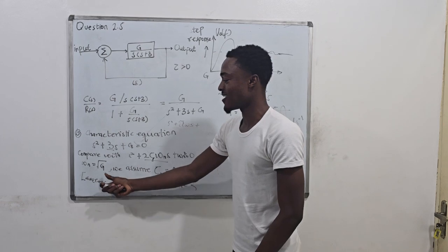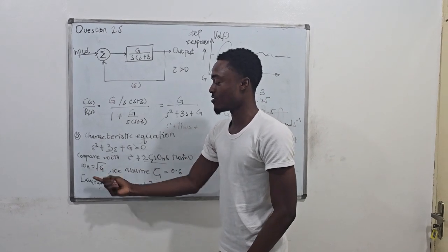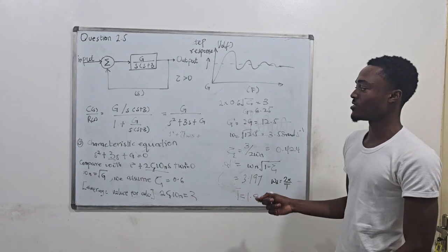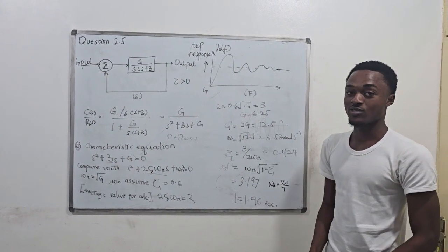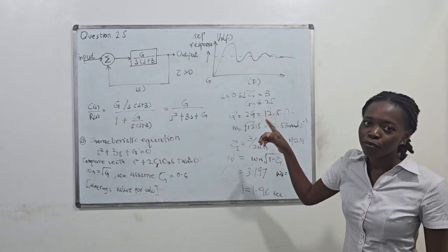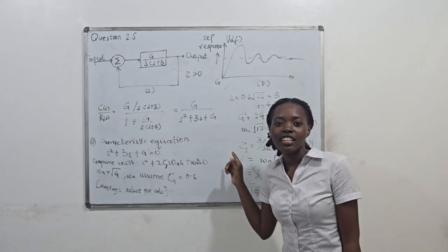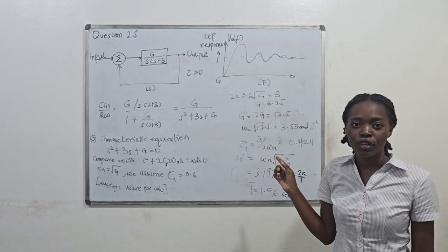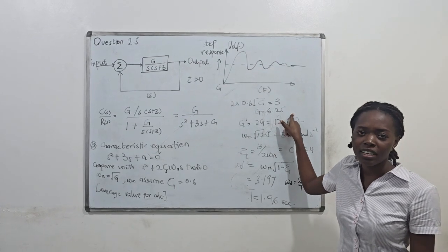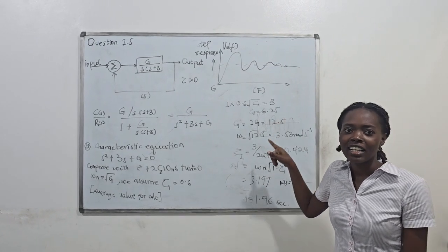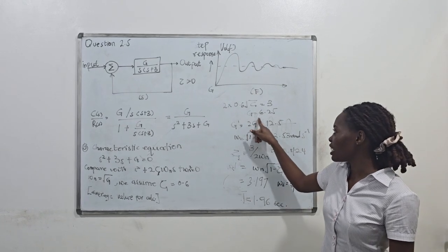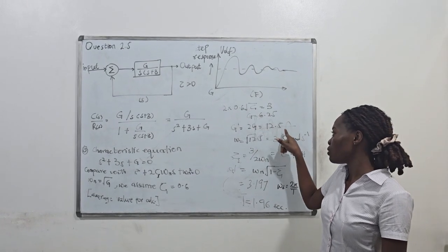So therefore, we are going to find the gain, and this is the equation given to us to find the gain. So we just substitute in the values and simplify, and we have the gain equal to 6.25. From the previous step, we established that the minimum value of G, the gain, needed in order for the system to exhibit overshoot is 6.25. And the problem asks us to consider the situation whereby the gain is twice the minimum value. So to do this, we simply multiply our gain by 2 to get 12.5.